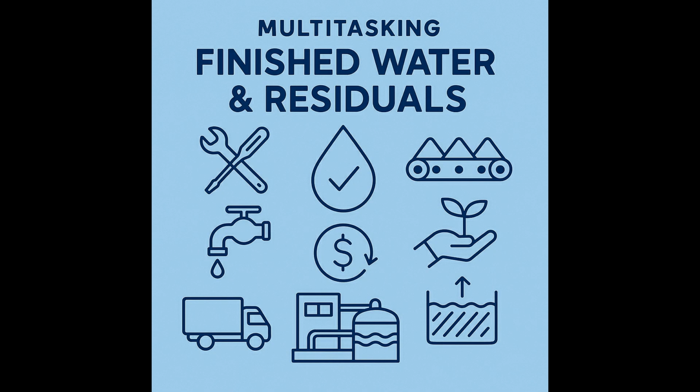3. Permit alignment is key. Know your VPA permit conditions cold. Understand soil monitoring needs, agronomic rate limits, seasonal restrictions, buffer zone requirements, metals testing frequency, and any current or pending PFAS language. Keep impeccable logs. Documentation is your best friend during inspections.